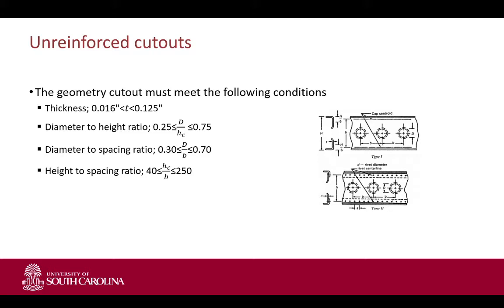Based on those graphs, you can determine the hole size, or if the height is fixed, the maximum hole size, and if the hole size is fixed, then you can determine the minimum height of your spar. Thickness will also play a role. A lot of things are very well defined, and you have to meet all the criteria in order to have a successful design.